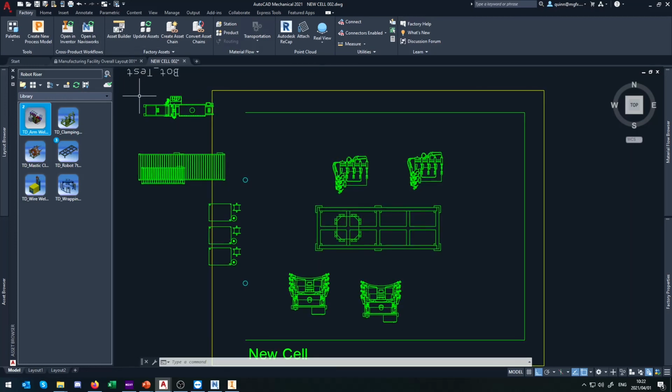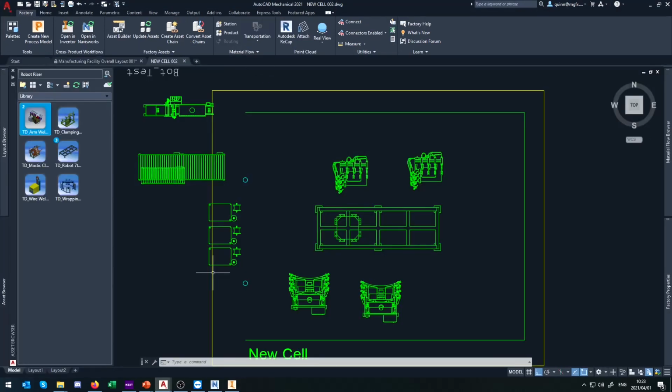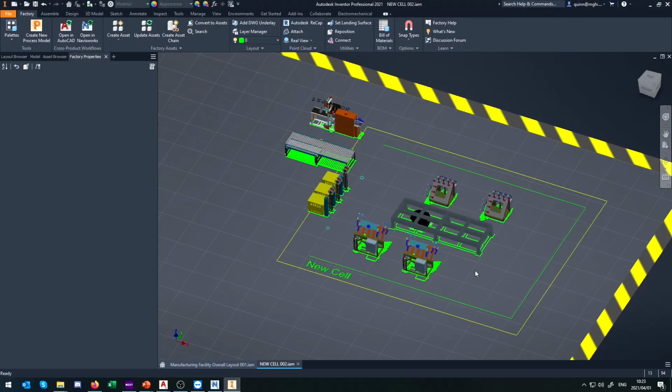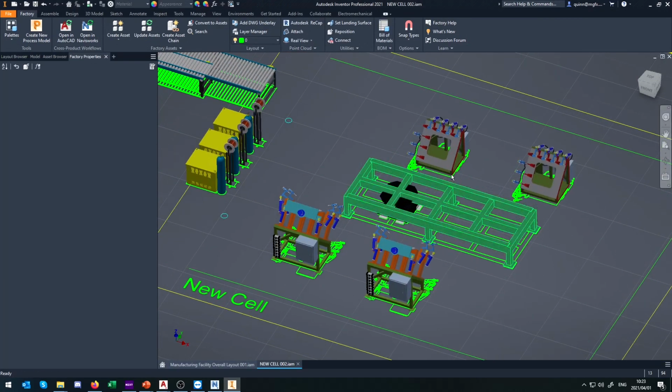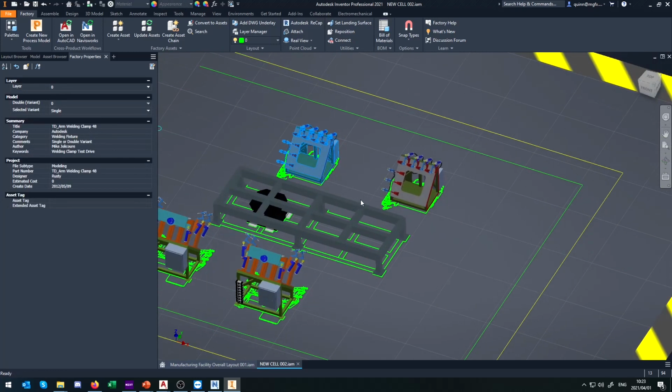And watch this. Remember I just showed you how this automatically builds, and that when we put our conveyors in, it automatically dropped our 2D views? Well, this is where it also gets quite cool, because of this bidirectional link. When I open it in Inventor now, watch, it also puts in my 2D view at the bottom. Like I said, it keeps jumping back there. But it also put our other stuff in, such as these other clamps, etc.